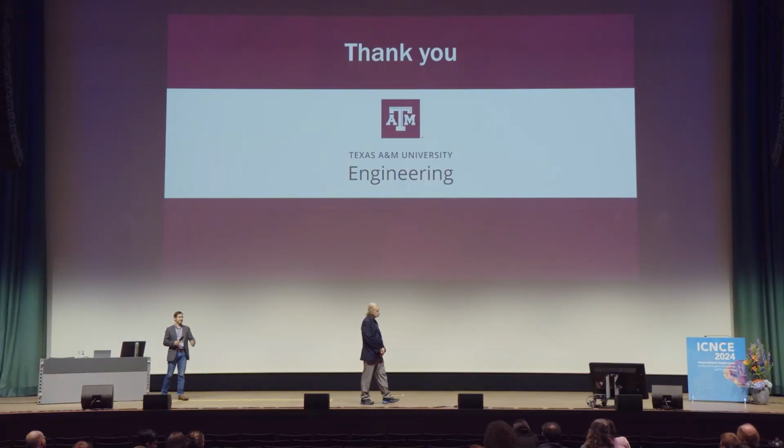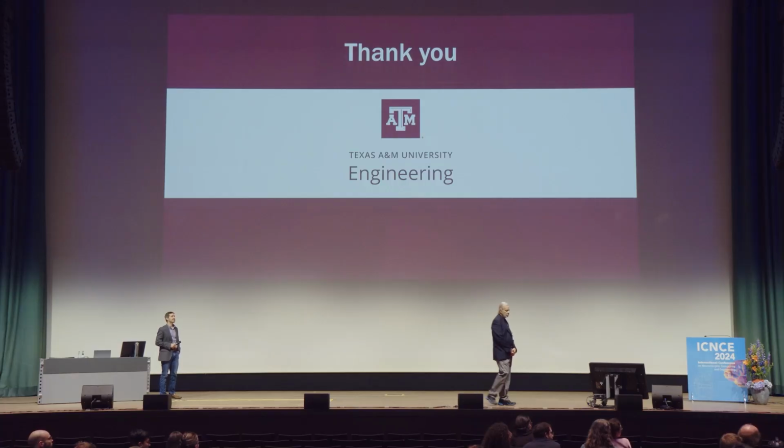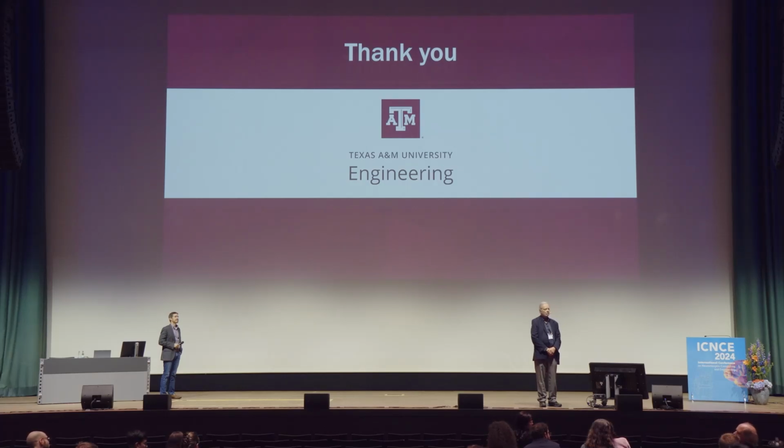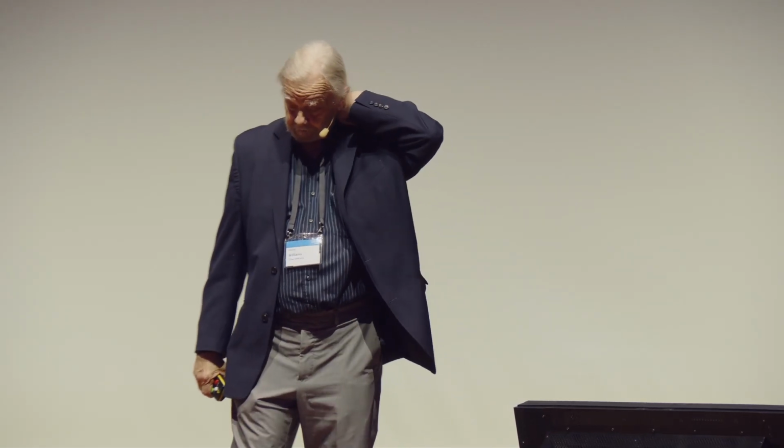Thanks, Ian. Thanks, Stan. My question is, your model, you're showing diffusion or movement due to the concentration gradient or current direction, but also thermal diffusion. Did you consider in the model that in the thermal diffusion, depending on material and mobile species, the direction of diffusion may be opposite? Well, I didn't show anything about diffusion at all in any of my equations. Now, the issue is that when you have a current channel form, you have a high temperature region within a material, and because of that high temperature region, you can create diffusion fields. In particular, you can create thermophoresis, and it's my contention that this thermophoresis is actually the mechanism by which forming occurs in a non-volatile memristor.